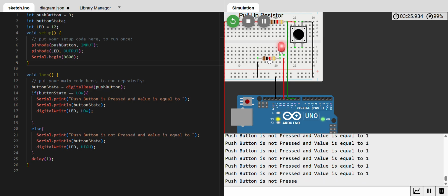Why we use only a 330 ohm resistor was discussed by me in the previous class, in the starting video. You guys watch that particular video. It depends upon the operating voltage of the LED and the forward current of the LED. All these parameters I have discussed and derived the resistance of this current limiting resistor.